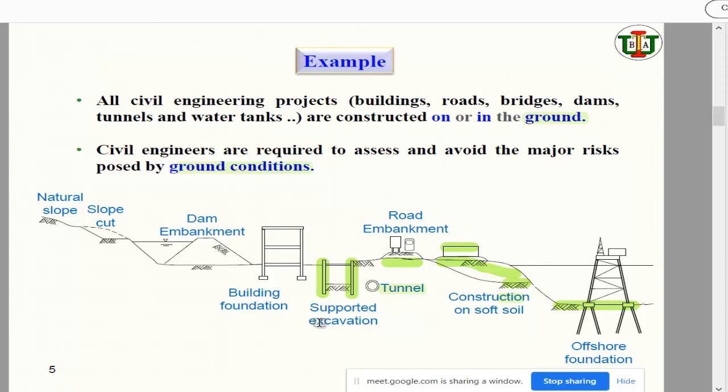Yeah, this is sheet pile, used to retain the soil. But here they are putting a mat foundation, this one, can you see? Yes, sir. They are putting a mat foundation, and this is a void, so that's why they need to retain the surrounding soil so it does not come here. So that's why they insert sheet pile.